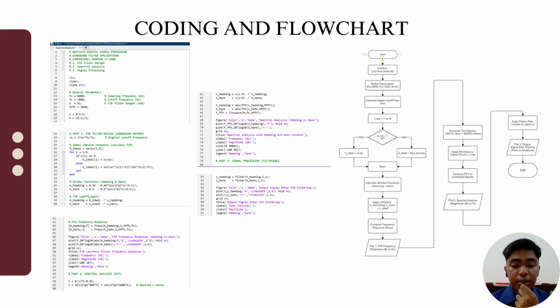The problem with this function is that it extends to infinity. If we just chop it off using the rectangular window, we get the Gibbs phenomenon, which causes massive ripple in our signal.